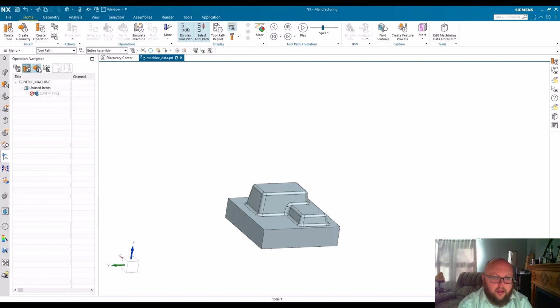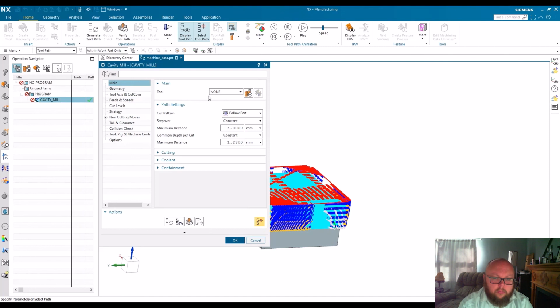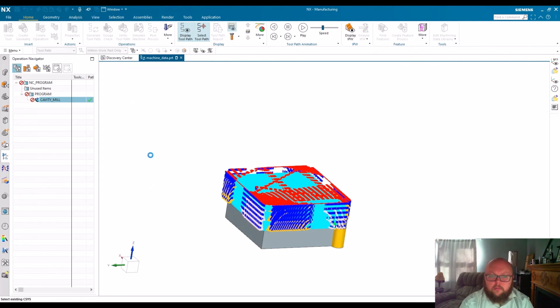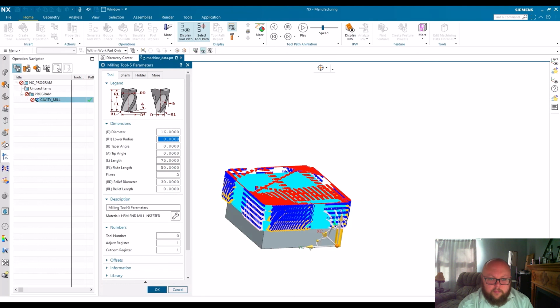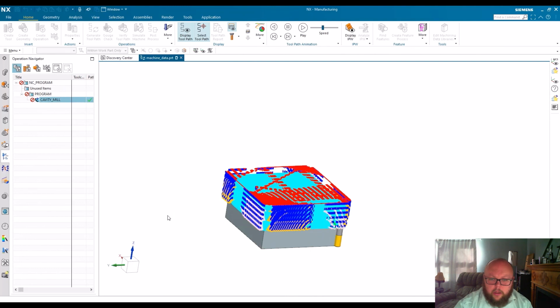Tool material, that'll come last here. We're going to create a new tool. And once we assign that, we are going to be using our new tool material type. We'll look at our operation here at some different information that already exists. In this case, we'll create our end mill, and we're going to assign the material now. Once we do that, we'll okay this dialog and see some results. And finally, go and choose our swoosh tool material that we just created.